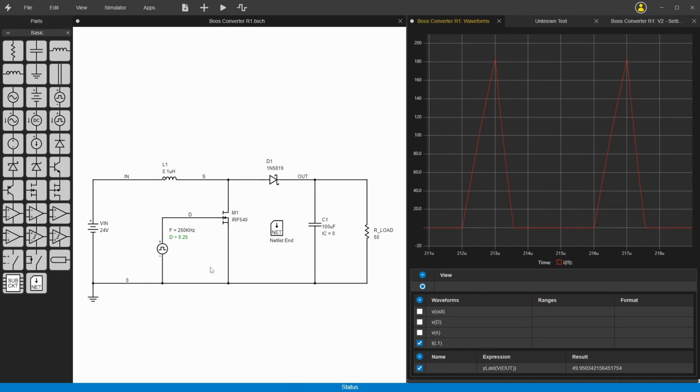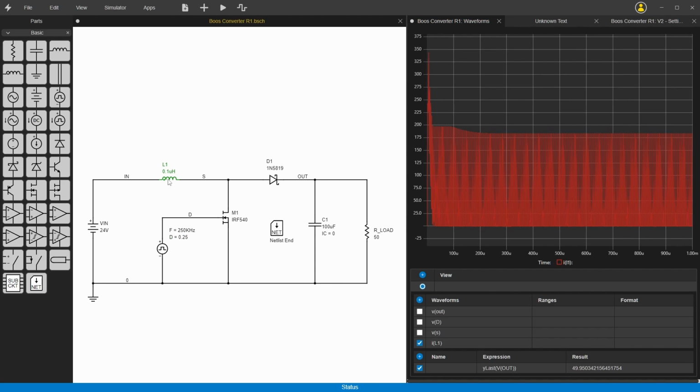So the last thing I wanted to mention is just a general sort of philosophy of how these are put together. So there's symbols, and there's wires, and there's nodes, and then there's labels. And the symbols are what create the lines in the netlist. The wires connect all the symbols together, and then the nodes are at each end of a wire and at every pin of a symbol.